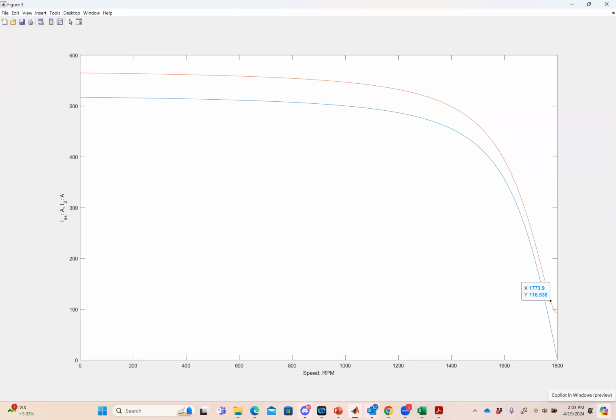Why would I call it the stall current? Yeah, when it's stalled. In fact, let me get to the torque curve. I'll talk about what I'm going to say. But the machine can stall during startup, all right? And it can get stuck there. It's really bad if the machine gets stuck at zero speed. If the machine stalls and gets stuck at zero speed, it's producing a lot of torque, trying to get itself going, but it's not able to move.